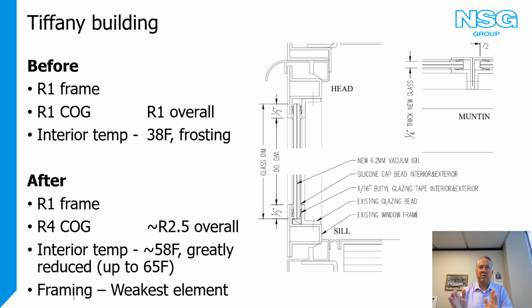So maybe that's not quite as high performance as a full replacement window would be, but it's still a significant improvement while it keeps the existing framing and minimizes your additional carbon improvements, and it makes some operational improvements as well. Takes that interior temp up to 58 degrees. Now you can sit within 2 or 3 feet comfortably. But the framing's still the weakest element. It needs to definitely be a part of the consideration.